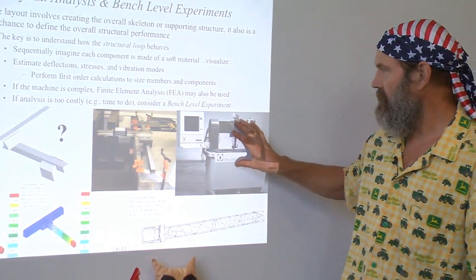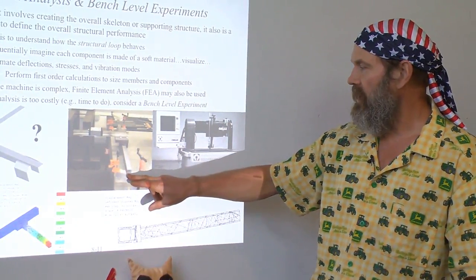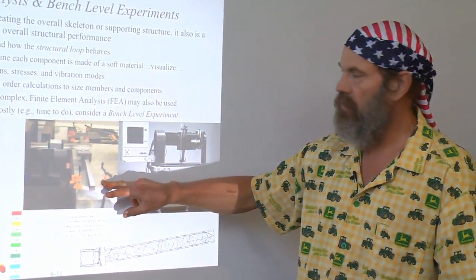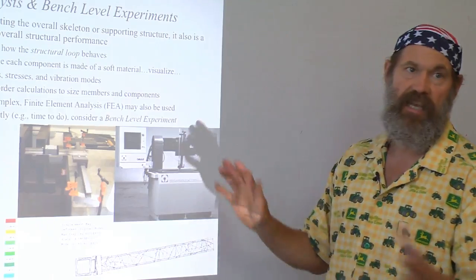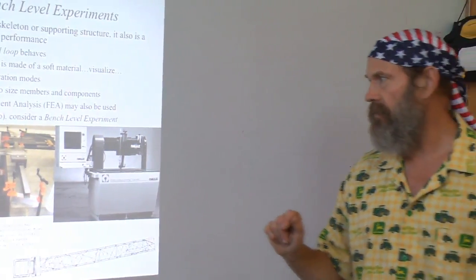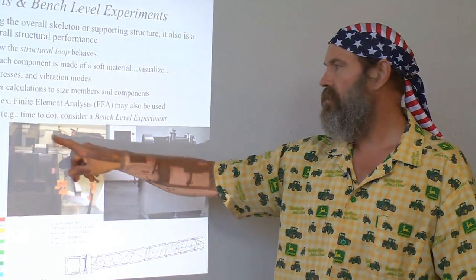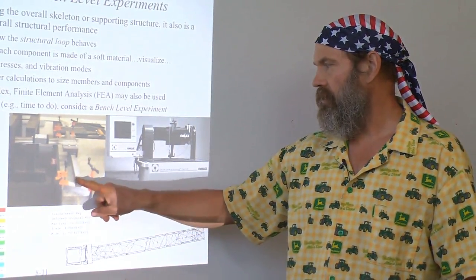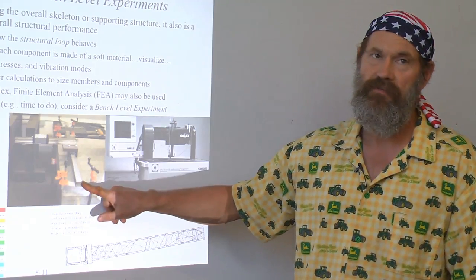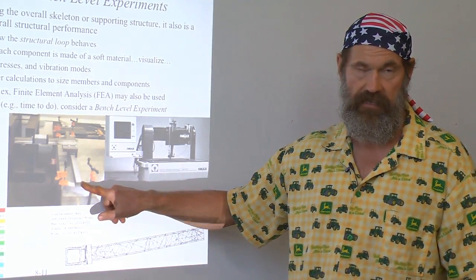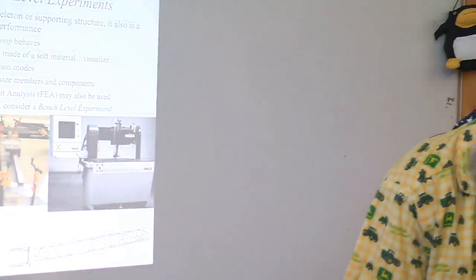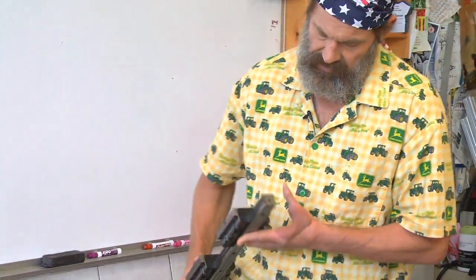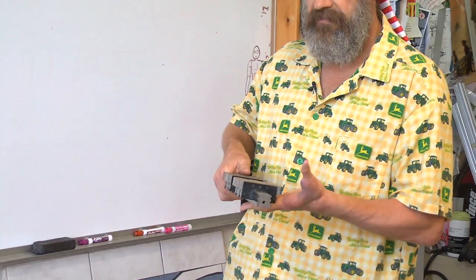For a small machine, can we take really giant, way oversized bearings and use the bearing block and the rail itself, and that's it? It turns out you actually can do that, and you can afford to do that, because some of these large bearings, this is a size 55 it's called for linear guide bearings, that we'll talk about when we talk in topic 10 about linear bearings. This one here, by the way, I believe was a size 35. So 55 is that much bigger.